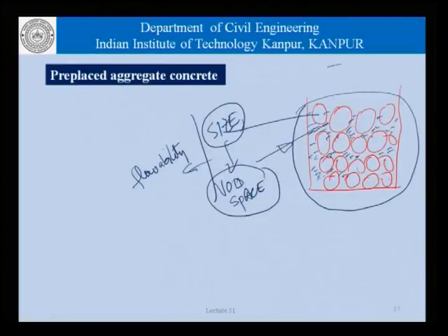Whether we take a pipe and just let the grout flow under gravity, filling the spaces here, or we try to push the grout under pressure from below. If we are pushing the grout from the top, there is a possibility that the grout might not reach all the spaces, whereas if we are pushing it from the bottom, the chances are that we would be able to accomplish a higher filling, even though it is more difficult to do.